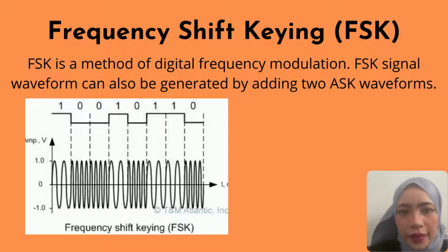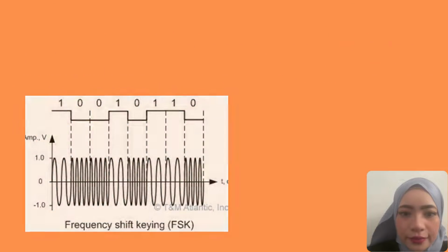So, is ASK or FSK better? Yes, FSK is better than ASK in the cases that the carrier has a constant amplitude and hence is used in communication systems where security reasons are considered. But this does not always apply due to it being faded and less reliable over long-distance communication. This is because its SNR decreases and hence produces low quality signals. That's why PSK, BPSK, QPSK, DPSK are introduced to overcome this disadvantage too. We are going to look into this topic next slide.